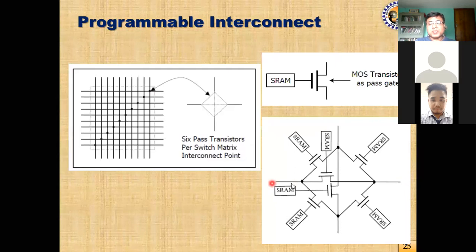So when we program, we actually store 1 and 0 in these flip-flops, so that accordingly the routing channels are established. I hope you have understood. So this is a simple MOS transistor. It is actually a fuse. That fuse in PLA or PAL we were handling with. So this is how the fuses are actually implemented in today's technology.